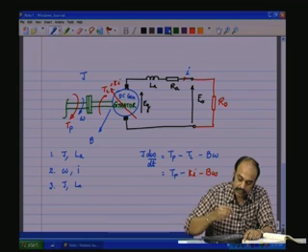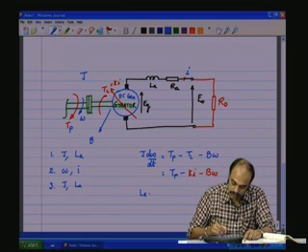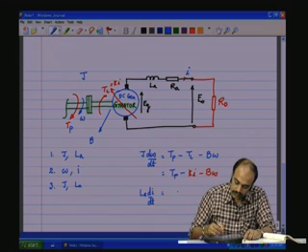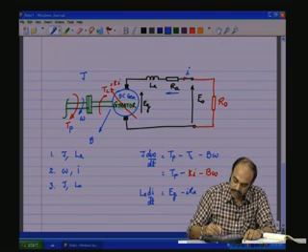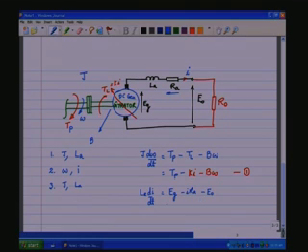Now, the second equation is on the electrical domain side. Again, that is also inductive. LA into d by dt of the flow variable, or the kinetic variable, which is i, is equal to the generated EMF Eg minus the drop across Ra minus the load voltage. But we have to express everything either in terms of input or state variables. Now, Eg is given by the cross-linked variable here, which is k omega. So, you have k omega minus i Ra minus i R naught, all expressed in terms of the state variables.